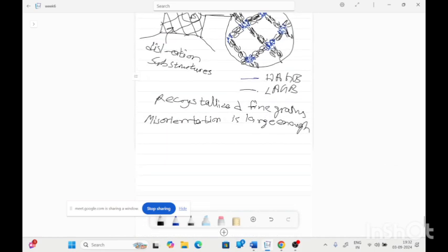So if the misorientation is large enough, an equiaxed microstructure can also be formed. As the misorientation becomes high, the process of grain refinement will occur all over the part, and that leads to equiaxed grain formation.